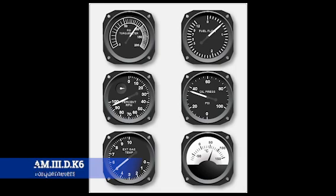So you'll hear, especially in the helicopter world, this becomes a really big deal because they are always looking at main rotor torque versus the engine torque. You want to keep the main rotor torque in a certain band, because if it gets below that, you stop producing lift, and the rotor starts to actually produce a lot of drag. You want to keep the engine torque under a certain limit because you don't want to over-torque the engine. And you also want to be making sufficient power, so you want to keep it above a certain range. But that's just in turbine helicopters.